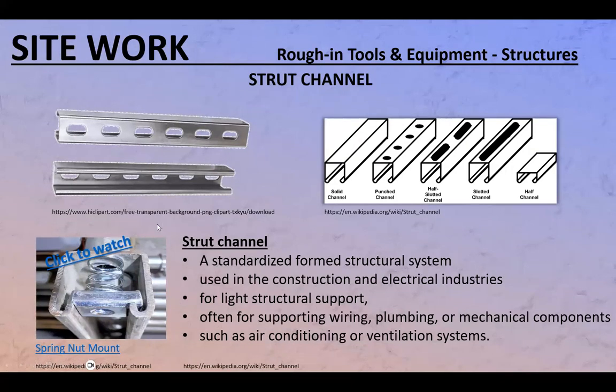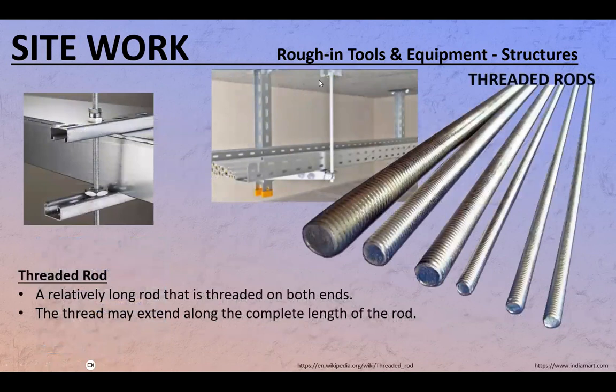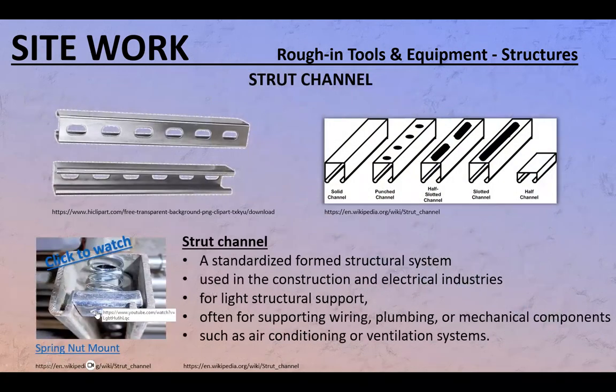So here's that. Now, here is a spring nut, right, over here. This is how things are being used. So if you just have that strut channel mounted in the ceiling, how do you mount threaded rods to that? Like, for example, here, or well, maybe not here, but you can suspend threaded rods through that using the spring nut. Right? Spring nut. How you mount it?